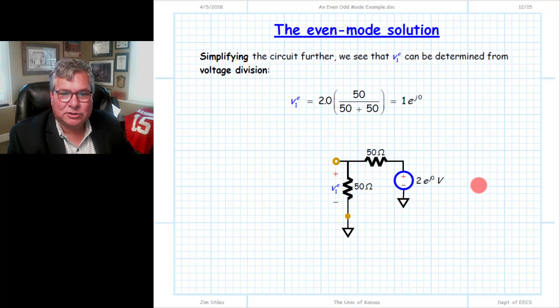So a circuit that looked so disconcerting and heinous at the beginning has reduced down to this, a simple voltage divider. Again, we have 50 ohms, the last 50 ohm resistor we've left off since it has nothing to do with the circuit. We go from this point directly to ground, and we have a simple voltage division problem. This is the voltage we're attempting to find, the V1.